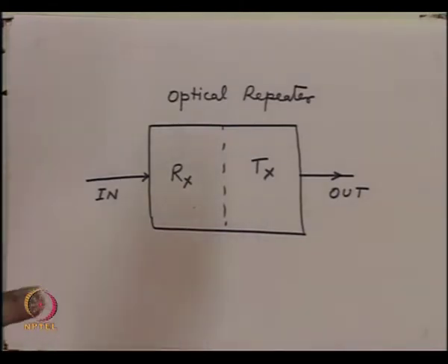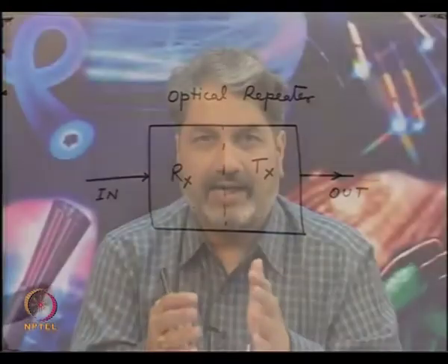So you have a substantial cost in a repeater, because you require the entire electronics which you require on the receiver side, and you will also have the transmitters which are exactly at the starting point. So for a long link, we are going to put transmitters and receivers periodically on a long optical communication link.